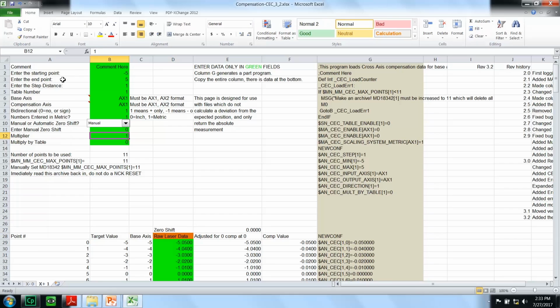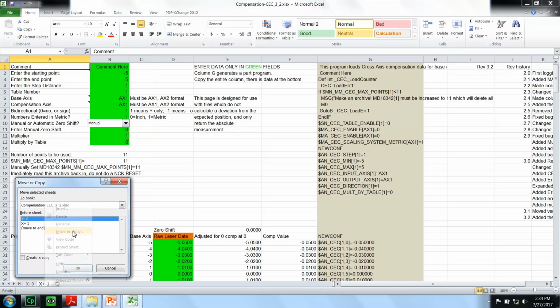So what we're going to do is repeat this for a rotary axis because, as described previously, we set rotary axis 0 based on a test bar and indicators, so that does need to be corrected. Let's add a rotary axis to these tables as tables 2 and 3, and we'll see how we deal with that. So the first thing I'm going to do is add 2 more sheets for tables 2 and 3. I'm going to add an A-axis.